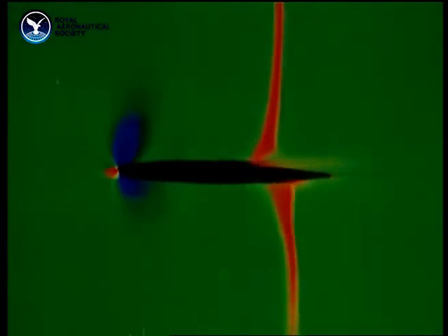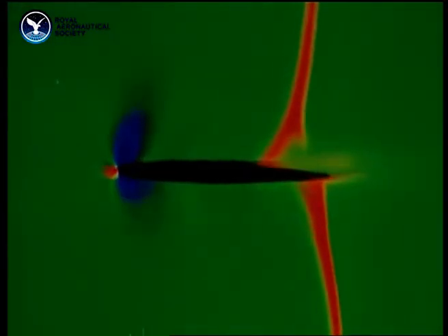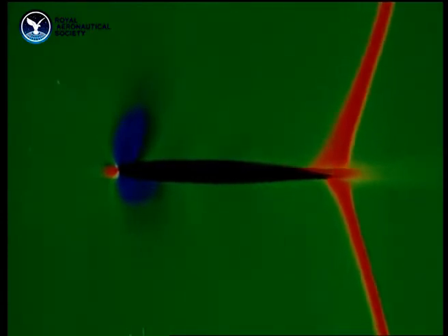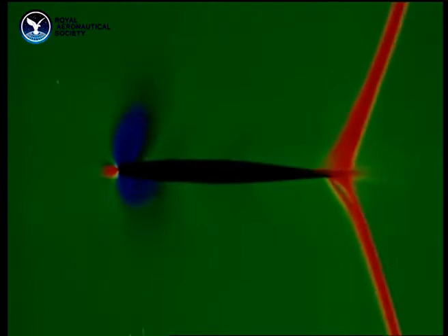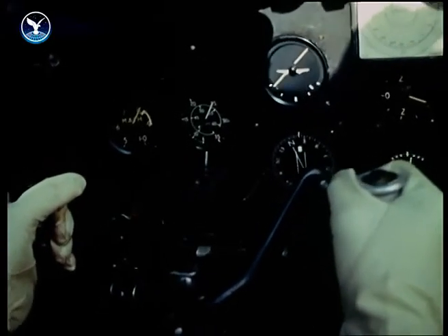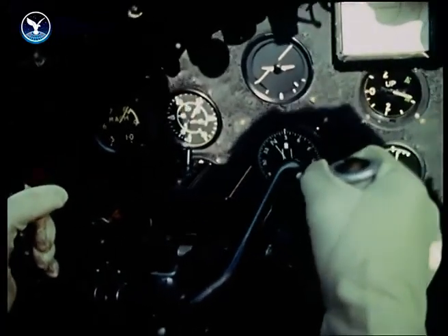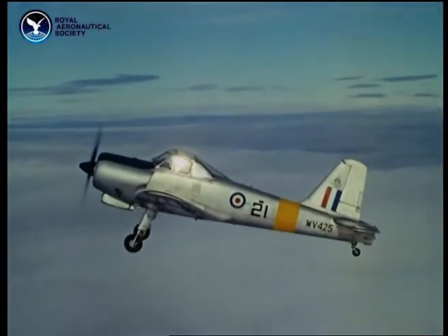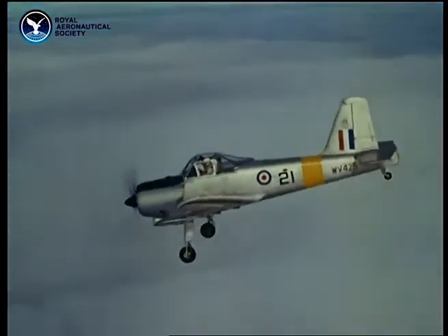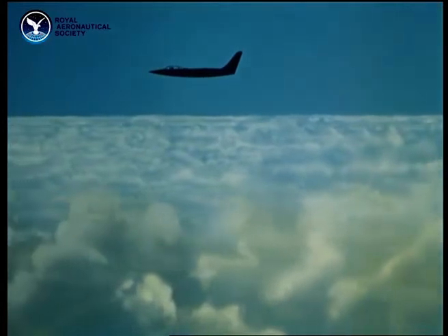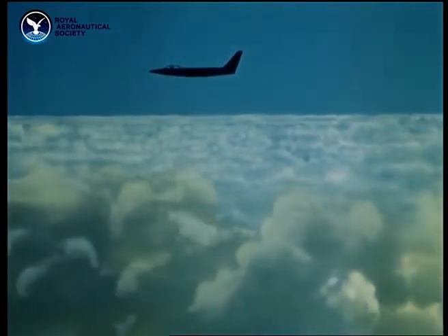But it is flow separation that causes most of the troubles in the earlier part of the transonic range, when separation is greatest. Once the shocks have reached the trailing edge, separation is much less. It is flow separation that causes the shock stall, so called because the effects in flight are rather like the normal low speed or high incidence stall, also caused by separation. The first shock stall trouble is a sharp rise in drag.